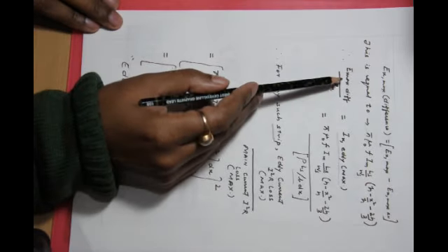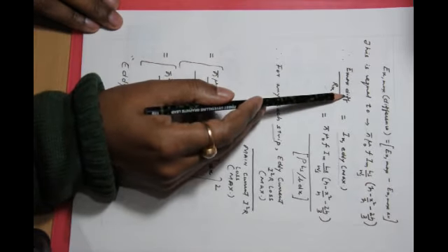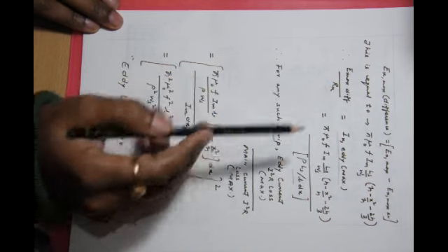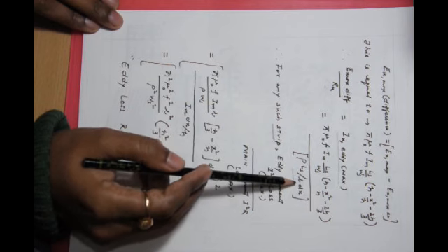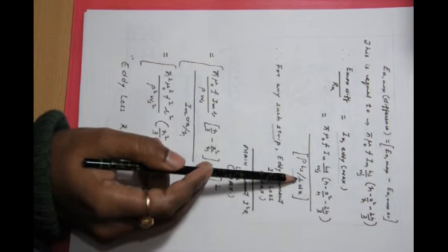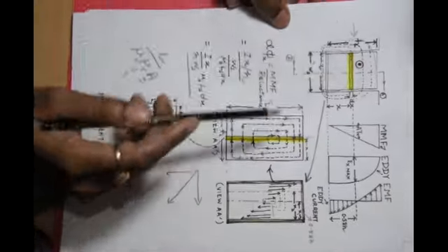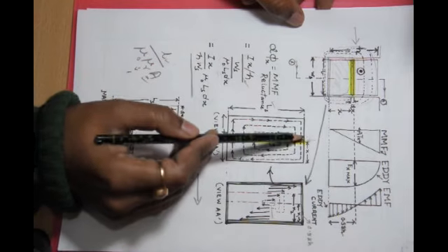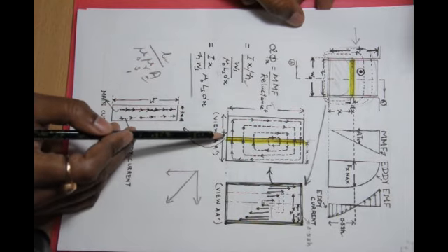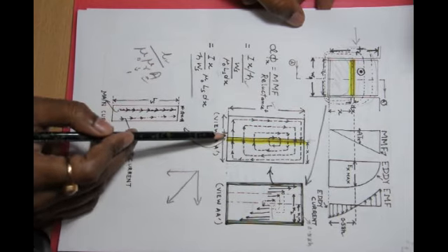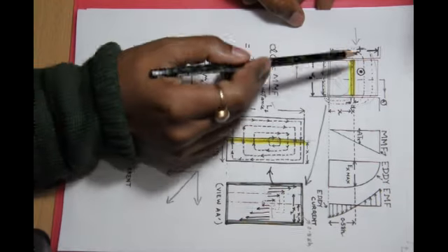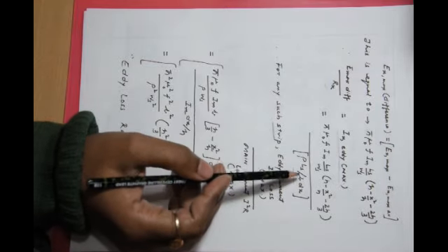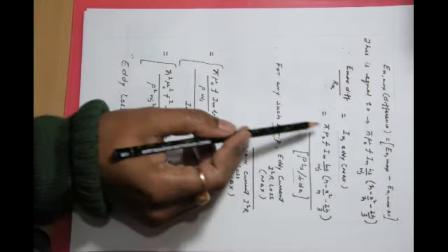So here we have calculated Emax difference divided by resistance Rx. Resistance of the element I have already told you, rho ls by bdx. How rho ls by bdx? B into dx is a section, and what is the length of the conductor? Length of this element is how much? Ls, and area is bdx. Rho ls by bdx. So this is the eddy current.